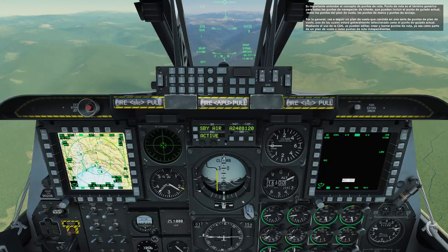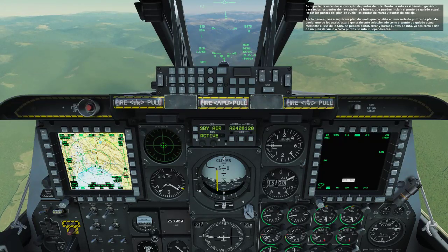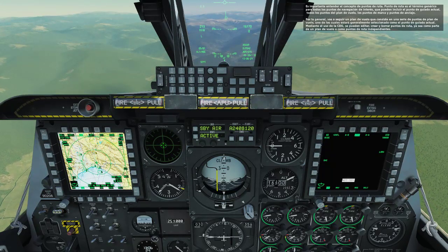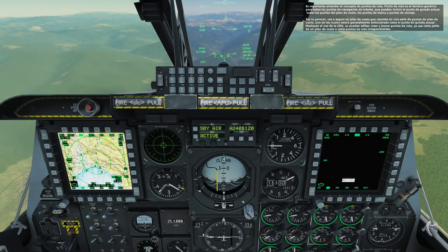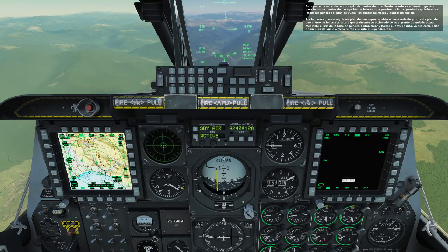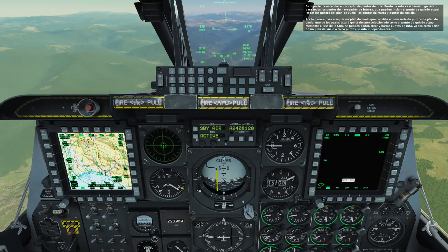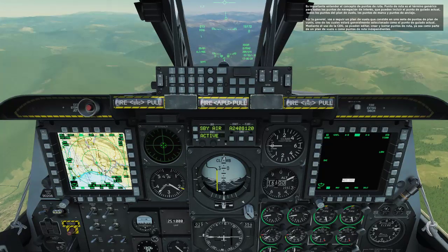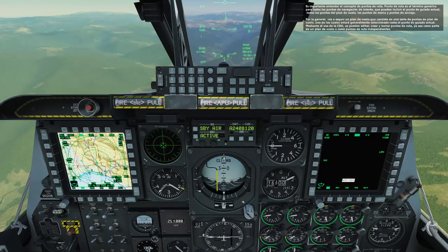It's important to understand the concept of waypoints. Waypoint is the generic term for all navigation points of interest, which can include the current steer point, all flight plan waypoints, mark points, and anchor points. Generally, you will be following a flight plan that consists of a number of flight plan waypoints, one of which will be usually selected as your current steer point. Using the CDU, you can edit, create, and delete waypoints either as part of a flight plan or as independent waypoints.